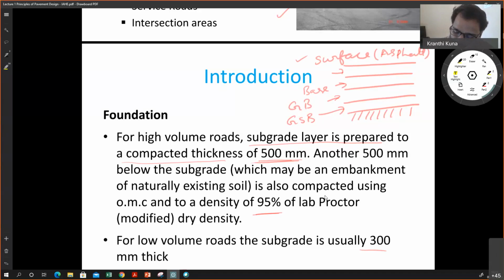Okay, you can have a cement treated base. If you have a cement treated base, although some people call it a composite pavement, we still call it a flexible pavement. Whereas instead of asphalt, if I have concrete slabs or continuously reinforced concrete, in general concrete material, cement, then we call it a rigid pavement. So the scope of this presentation will focus mostly on flexible pavement, which is primarily the asphalt pavements.